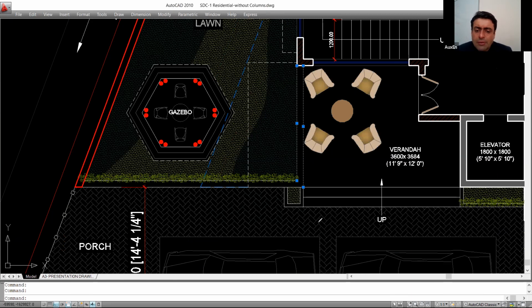So if the plinth is plus 0.45, and now you are climbing down, 1 step, 2 risers. What level will you reach? What will be the level of this lawn? So the level of this lawn will be 0.15. I hope this is clear. Now this was one step, but I think these are 2 risers that you can see. One is this riser, one is this riser. So 300 mm you are going down. So if this was plus 0.45 meter, this level becomes plus 0.15 meter.